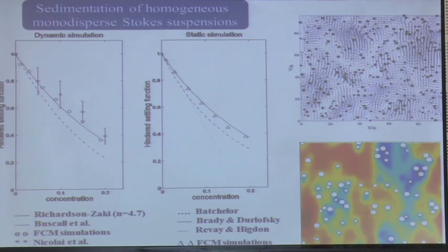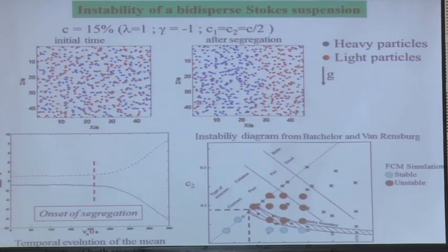But you don't have the effect of the wall. So maybe you have big recirculation into the system that I don't have in that simulation. So this is why you need to do what we call multi-scale analysis. You need to know the physics at the microscopic scale, but you need also to handle the whole domain, because you may have structures of the flow which are very big. Okay? So we look at different phenomena.